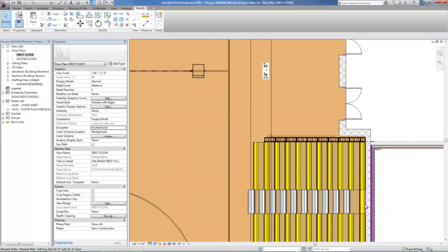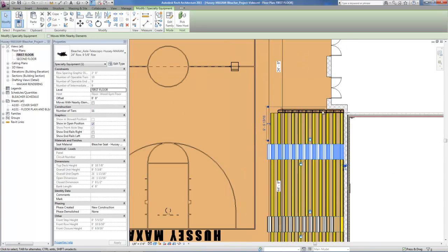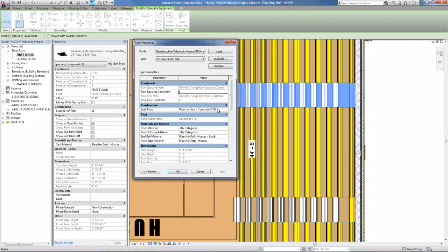And there it went. Then you have to repeat the same process for the aisle family, which will again occur for all of the aisle families of this type. So you would change those to the XC12, and then the top row of seats at the top of the aisles will update to be the XC12 as well.